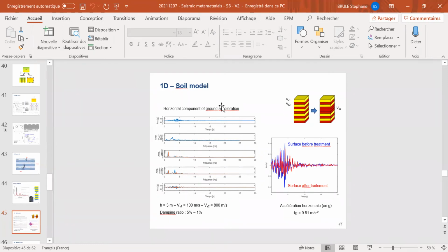So it's quite difficult, as you know better than me, obviously, all the difficulty to define this parameter. For buildings we know it could be 2 or 5%, because we don't observe a lot of cycles of vibration. But for the soil, we have very few experiments, and we have to test the soil for all the frequencies, as the damping ratio is frequency dependent too. I recognize that the study is only parametric.